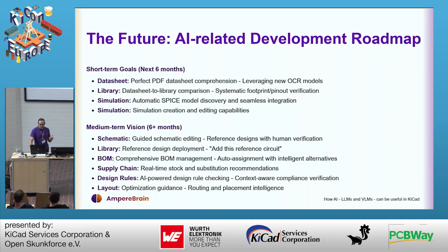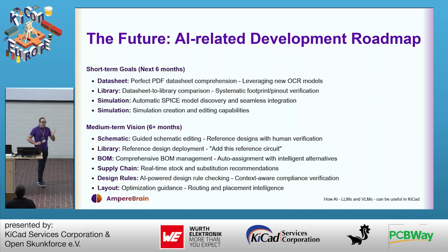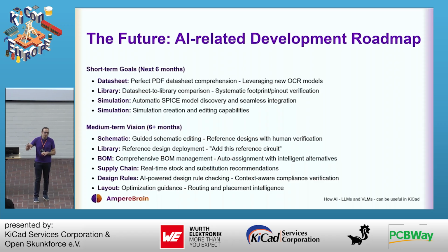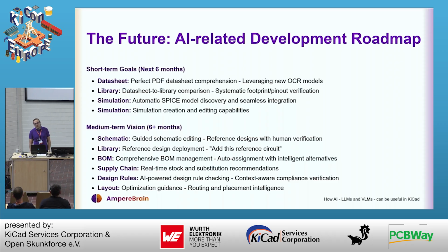I think I've been taking quite a lot of time already. As I said, I'm going to work a bit on the datasheet. Another thing is something simple: having the footprints. I know that you usually check your footprints before manufacturing, so just asking, what's my KiCad footprint? What's the datasheet footprint? Do they actually match? I think that's a very simple check to do, and searching for that in the datasheet is definitely not valuable time.